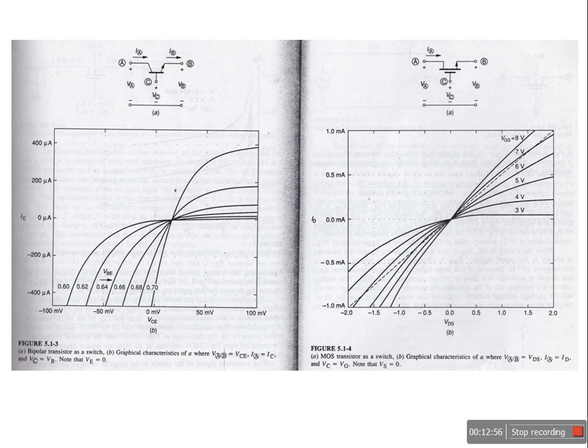So we have to plot the graph between VAB, that is voltage between the terminals A and B, and IA, that is collector current. So this is the graph here. On the x-axis we have put VCE, collector emitter voltage. Yes, definitely it is collector and emitter voltage, that is voltage across the switch. On the y-axis we have plotted IC, collector current, that is in terms of the switch, the IA, the current through terminal A.